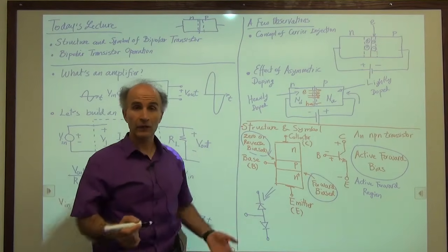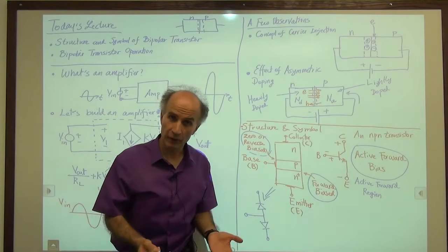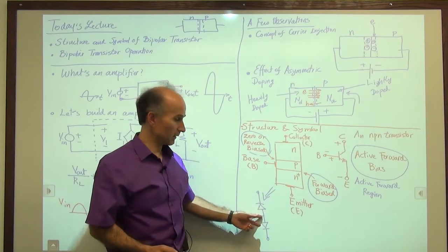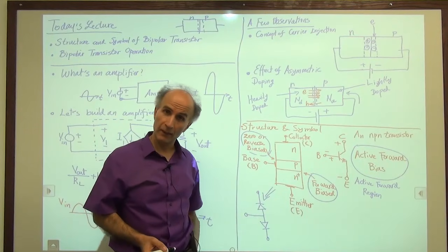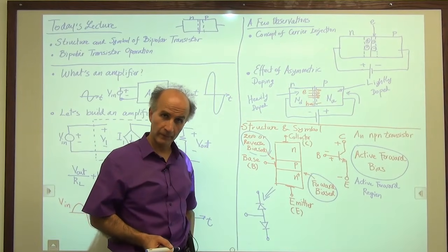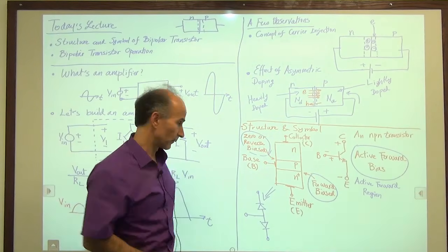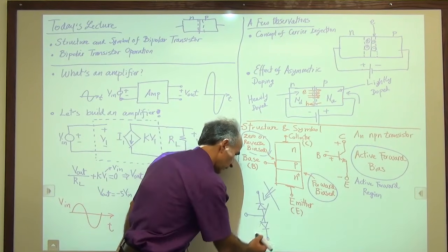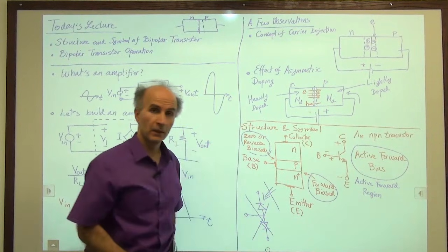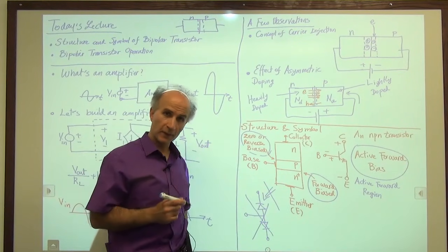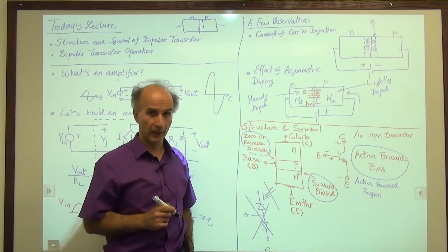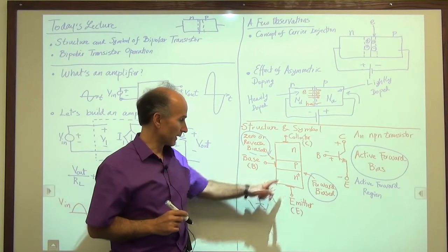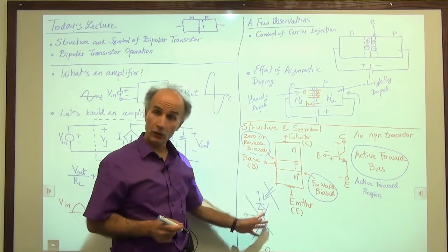Right? So actually I don't need to buy a bipolar transistor from the market. I can go buy two diodes and hook them up like this, and that should operate as a bipolar transistor. But unfortunately that is not true. So this is not true, and this is not a bipolar transistor. As we study bipolar transistors, we will see that this would not operate as that. So that's a word of caution, not to get confused between this and this, even though they look very similar.